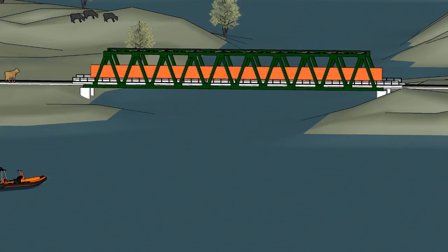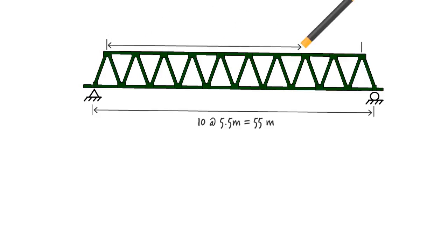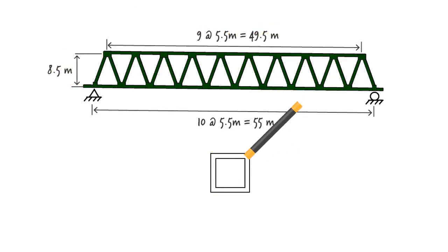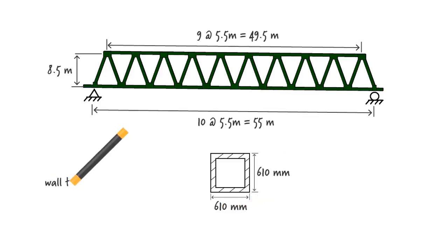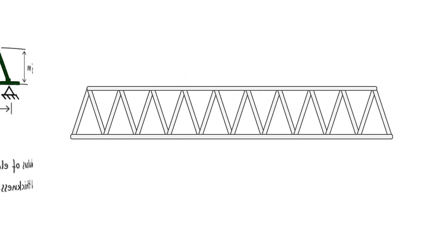Given the symmetrical nature of the bridge and the load, we only need to consider one of the trusses. Here, we assume the bridge is pin-connected at the left end and rests on a roller at the right end. Knowing the dimensions of the truss, we are now ready to perform the required analysis. Although we don't need to have section and material properties of the truss members for our purposes in this lecture, they would be needed for calculating joint displacements and member stresses when designing the bridge.